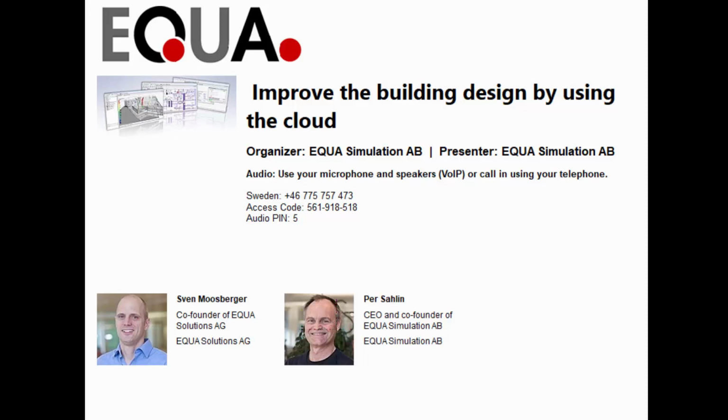If you have a very small number of parameters, this is possible. But as soon as you have more parameters and larger resolutions of what parameters you want to run, this becomes exorbitant. You can't do it. You have to do something else. One thing you can do is to run just a few of those cases. That's usually called a Monte Carlo run, a statistical selection, and we will show you that. Another one is a sensitivity run, where you change each parameter once essentially, and we'll show you that.